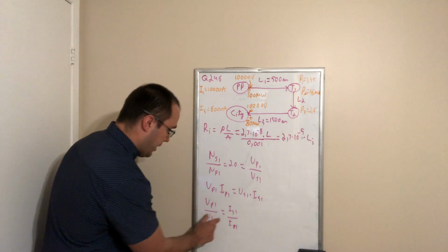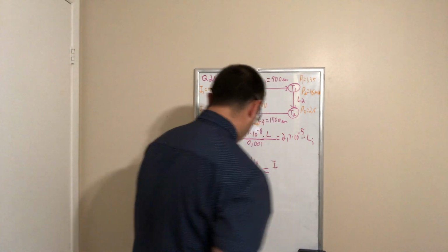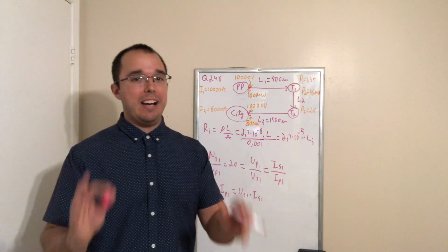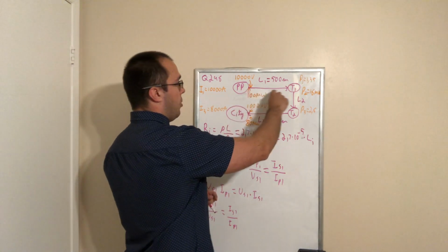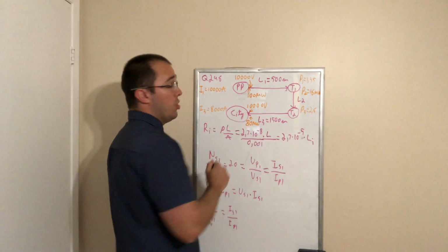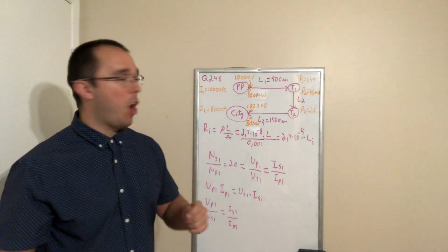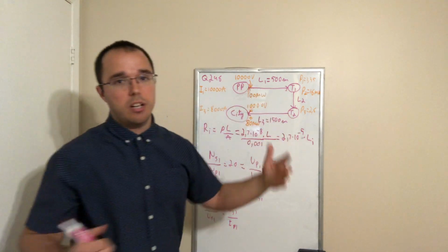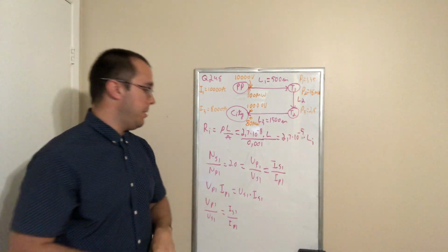So that means we take that term, it is equal to IS1 over IP1. Now, by the way, in these types of problems, I highly encourage you to use the current. The reason why is that the current is stable in each of the 3 wires. The voltage changes. There's a voltage drop in each wire, so it's not obvious at all to find the voltage drop on these. You can do it, but it's many extra steps that aren't needed. That's what I mean.